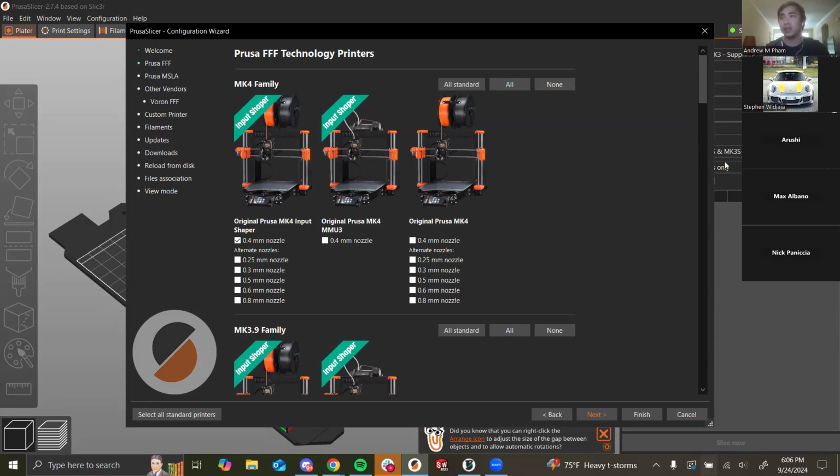So if you're doing FEA, ABS is not a bad material to go with. PETG, I think, is a little bit stiffer than ABS, but it doesn't have a great temperature resistance, which is why I don't generally use it. I'm going to be talking about materials a little bit next week, but just to get a general idea, something like an ABS would work.